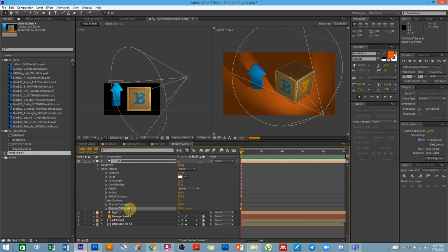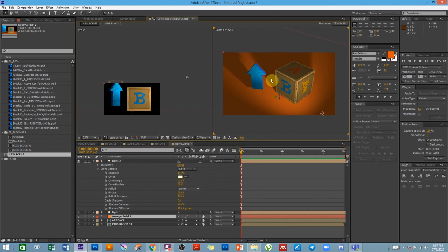You can even adjust the shadow darkness, but as you can see, After Effects is not really suitable for making 3D objects. You can see it's really laggy. I'm just so afraid to even move the camera right now. If I were you, I would not activate all this shadow stuff until I've done animating. But sometimes it's quite tricky, right?